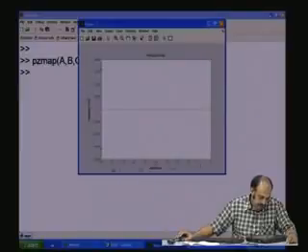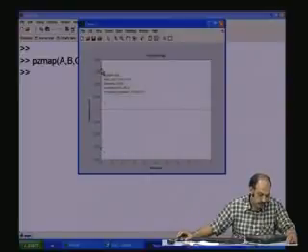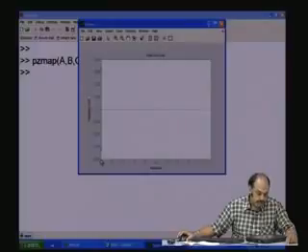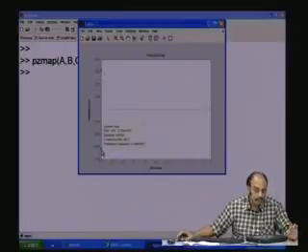You see that at minus 50 you have a pole, two poles. There are two poles, one pole at the positive side of the omega axis, and one pole on the negative side of the omega axis. They are exactly at the same position as far as the projection on the real axis is concerned, and they mirror each other. So, whenever you get a complex pole, you should have another mirror image complex pole on the other side of the real axis.